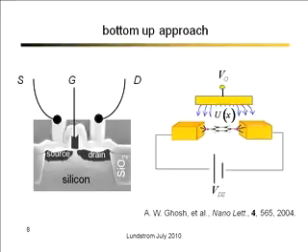And it's very difficult to take the sort of textbook understanding of MOSFETs and predict the IV characteristics of a molecular transistor. But using these bottom-up ideas, you could describe both devices, a silicon MOSFET or a molecular transistor, using the same concepts. And you could compare the two and decide whether it makes sense to try to build a molecular transistor or not.